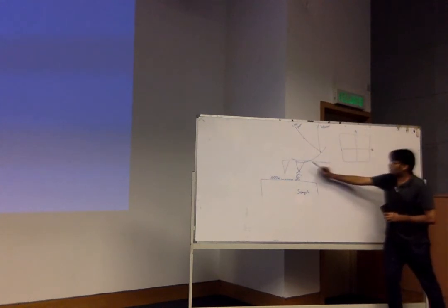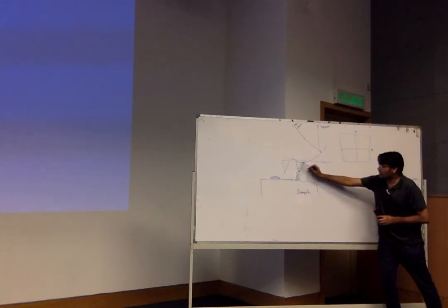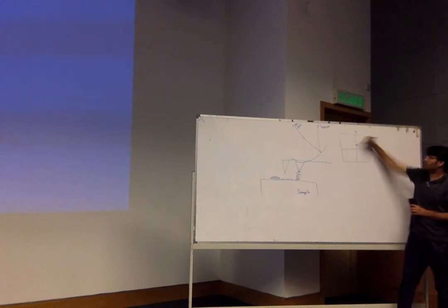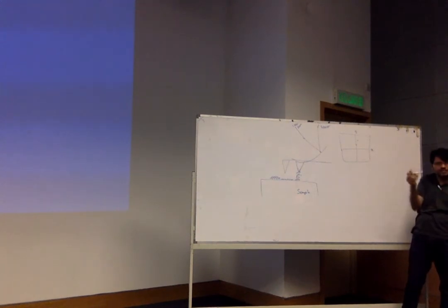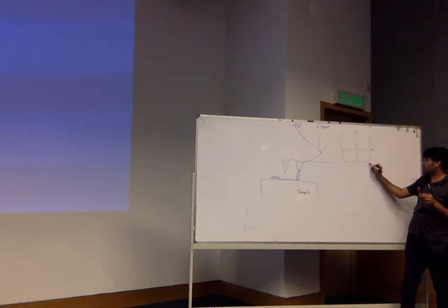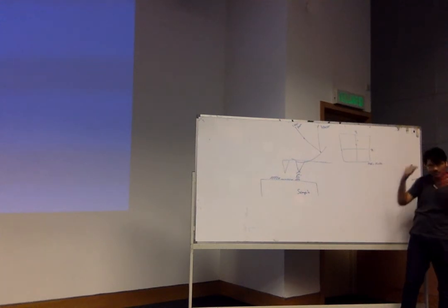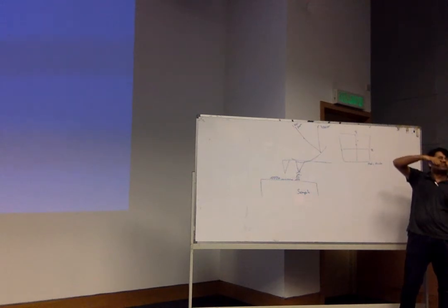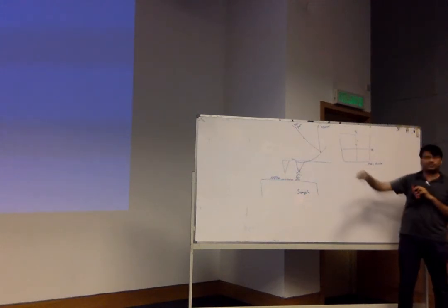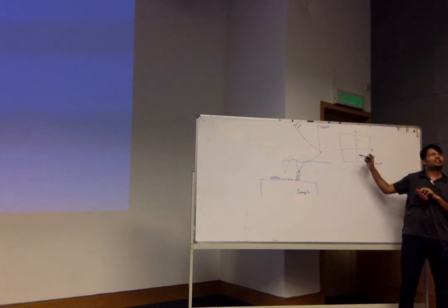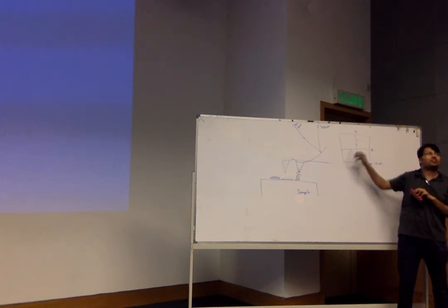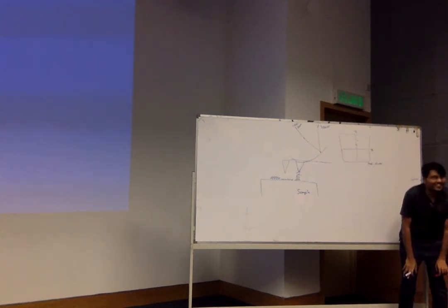At one point, when there is very little bending, say the spot appears here. But when there is more bending, the spot appears here. So based on where this laser beam hits, and this is the photodiode here, based on this reflection of the light, you can imagine that the surface profile can be imaged. Do you understand?